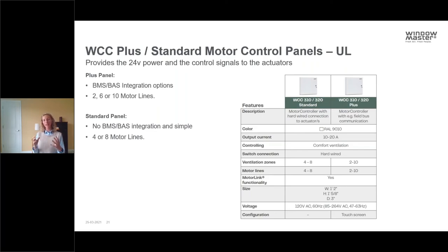But high level and in general guidance, I would say don't put the control panel more than 150 to 160 feet away from the furthest away controlled actuator. These control panels can typically be located in a place like an IDF closet, an IT room, a mechanical room, a storage closet. This is really something that together as a design team, you talk about, also with your electrical contractor, where do you have space, and then you take it from there.